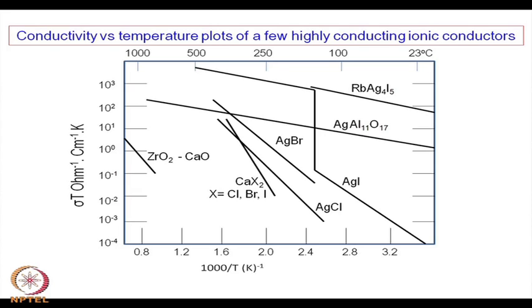And in fact, in sensor applications and fuel cells, we will see that it is the zirconia yttria system that is more preferred than zirconia calcia, and in some cases zirconia scandia, Sc2O3, is also added, and the conductivity is in fact much higher, although it is a little costly, and so for economic reasons it is not used that much.